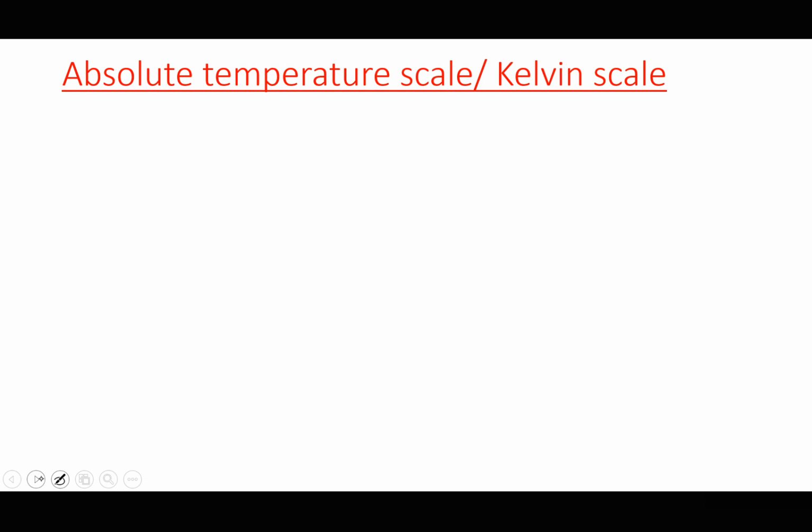So when we are setting it up, we do not rely on any particular property of any particular substance. Note very carefully that one of its points is very significant, and we call it the absolute zero. It is more significant than the fixed points of the centigrade scale, which are actually variable, or can change when there are impurities. When the pressure changes, the ice point or the steam point could change. But the absolute zero does not depend on any particular substance.